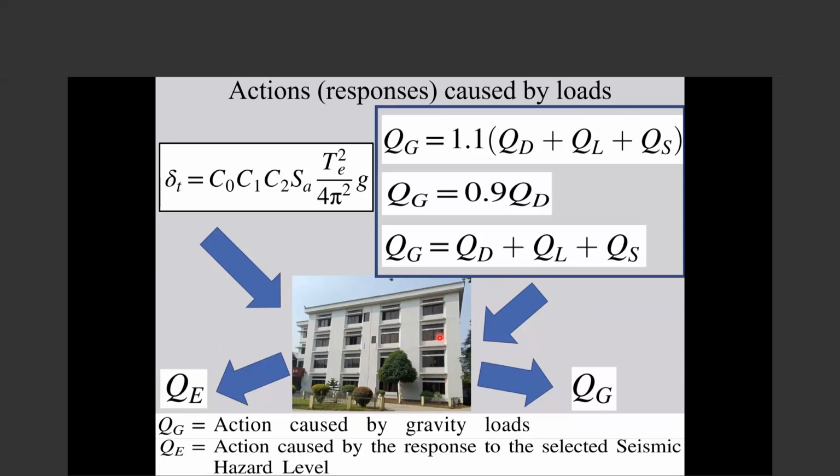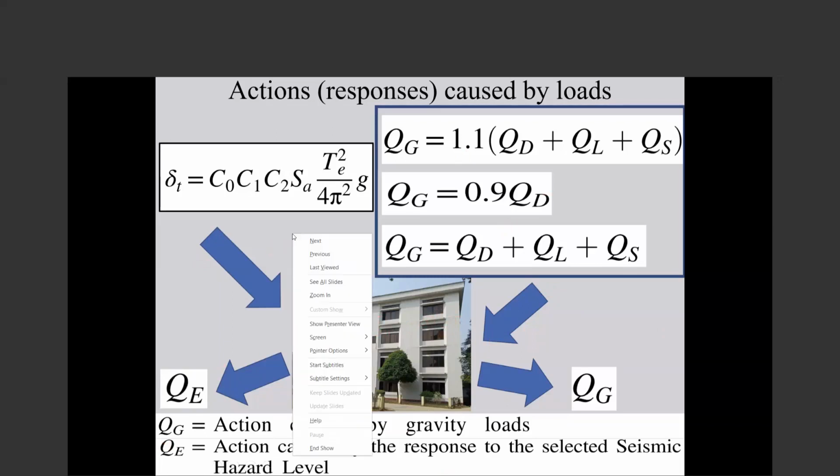But if it reached the target displacement, and no force control action in an element reaches the lower bound strength, in an element we have different actions, then we can look at the deformation control actions and how much damage they do. If none of them pass the yield, the system is elastic. If some of them pass the yield, then we look at how much damage. And then we know we need the strengths, the capacities. But now it is the demand. The demand is done. Now we have the effect of the earthquake on this.